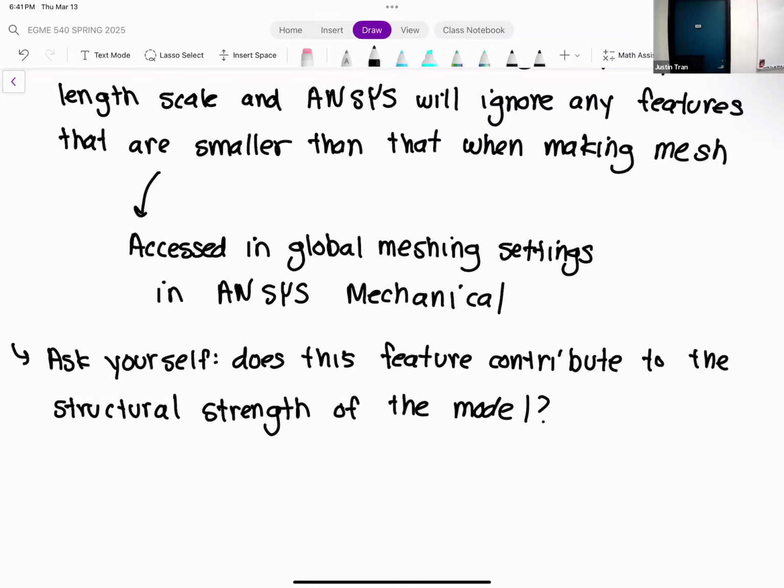That's actually not for deformation. Remember the shell elements also solve for the orientation, so I think that's just illustrating that. It looks good, but let's look at it again. One way you can fix it is to change that displacement support to just a fixed support. I think that's one of the data points too, and I think people are getting much better results. But it looked good to me, but if you wanted me to look at it again.